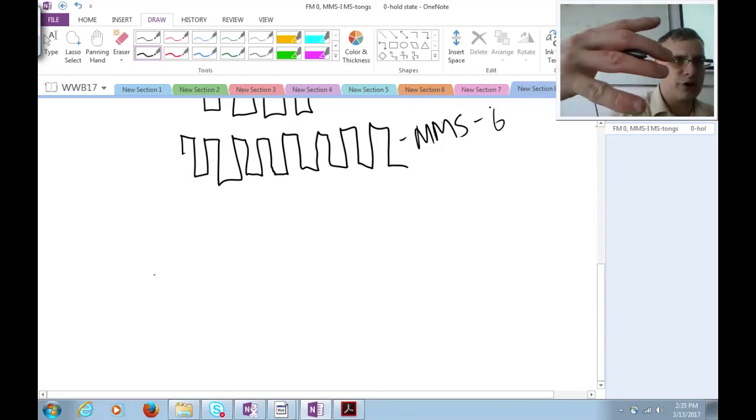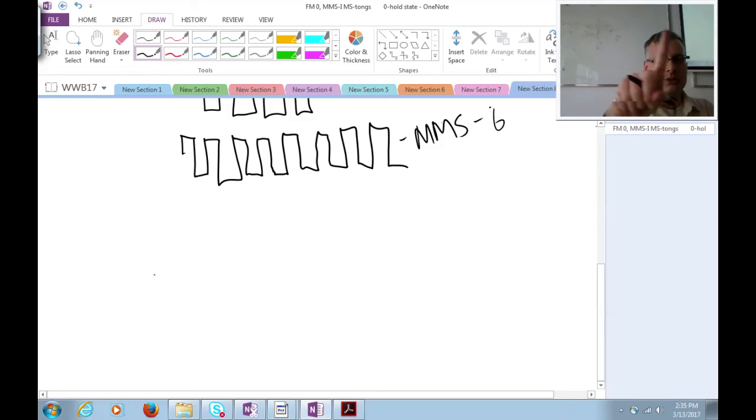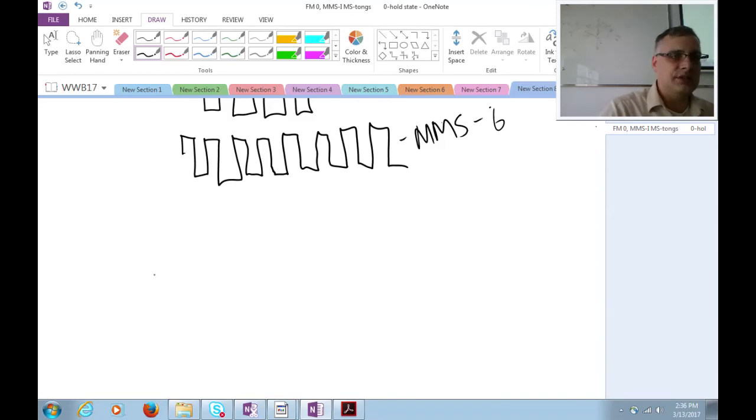So what that winds up looking like is basically subcarrier modulation, where again the signals are just pushed over to the edge. But this Miller pre-coding kind of distorts the signal and actually gets a little bit of extra signal strength away from DC. And that's really all that step does.